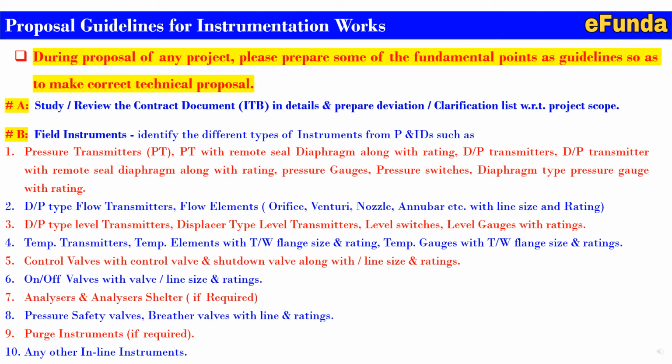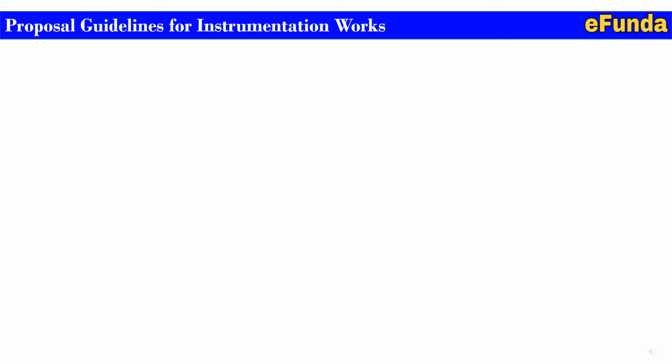These are the fundamentals while choosing the field instruments based on the PNIDs. With this identification, one will get the count of each instrument related to flow, level, pressure, temperature and any other final elements if required. We have seen field instruments.